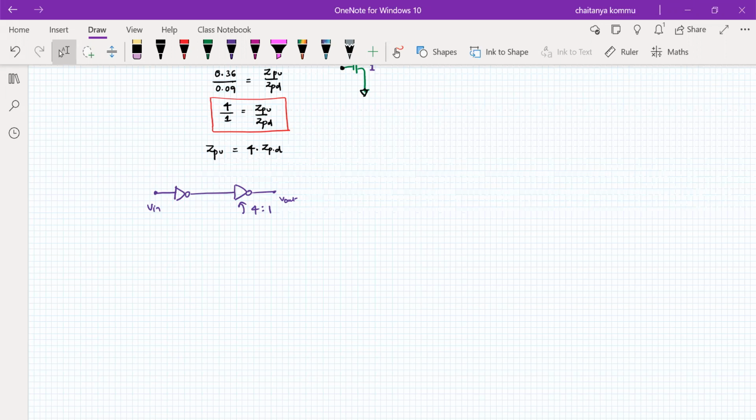Why? Because there are two reasons. Since a depletion mode type of transistor is always on, because the channel is already present, as soon as the power supply is given to the transistor, it is automatically on. Therefore, we have to deplete the charge, deplete the channel, so that we can utilize it. That means the opposite inversion of that particular enhancement mode. So there is a problem with the depletion type mode transistor. Another problem is that the short circuit power consumption is high.